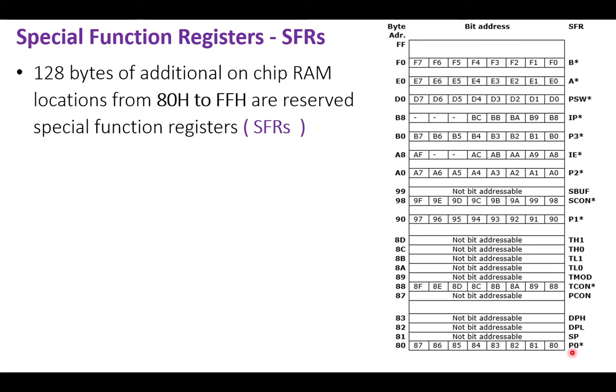80 is the address of port 0. 81 is the address of the stack pointer special function register. 82 is the address of data pointer low. 83 is the address of data pointer high.